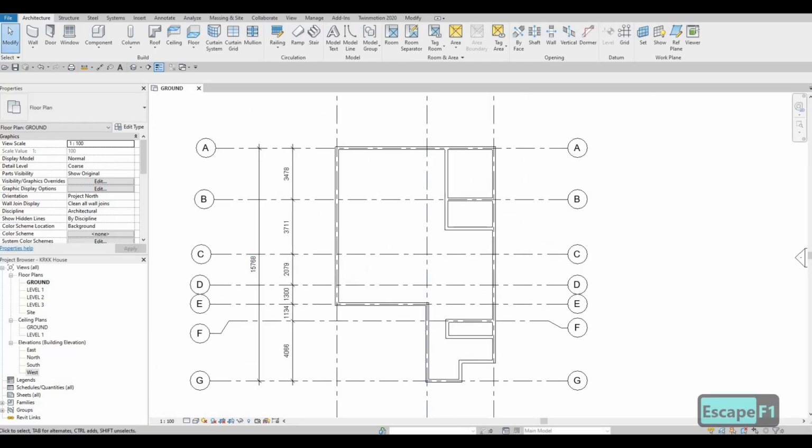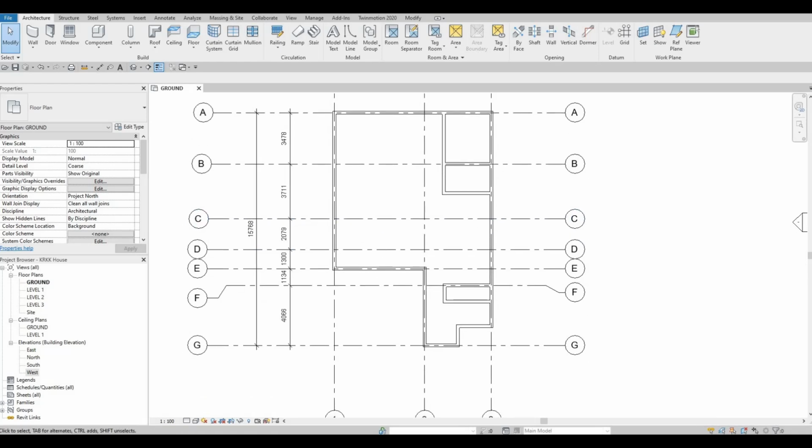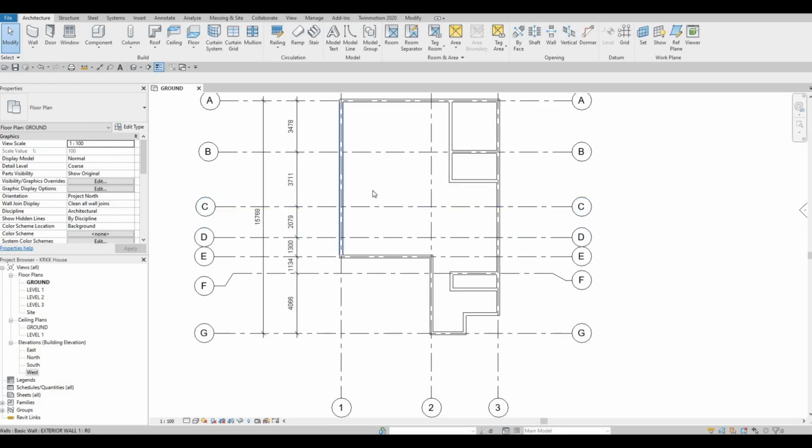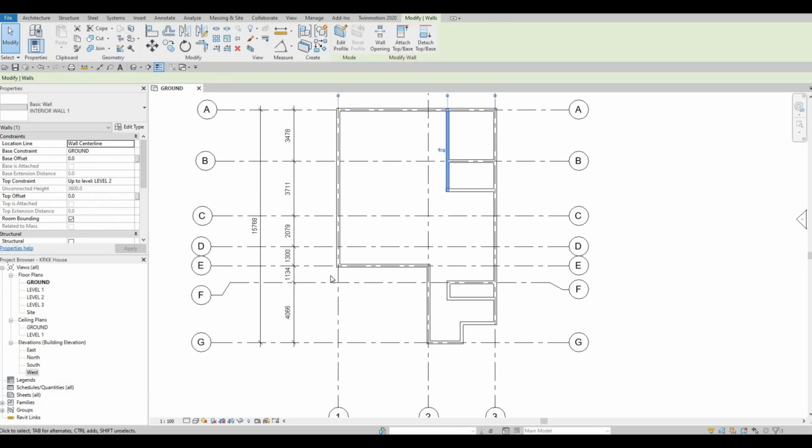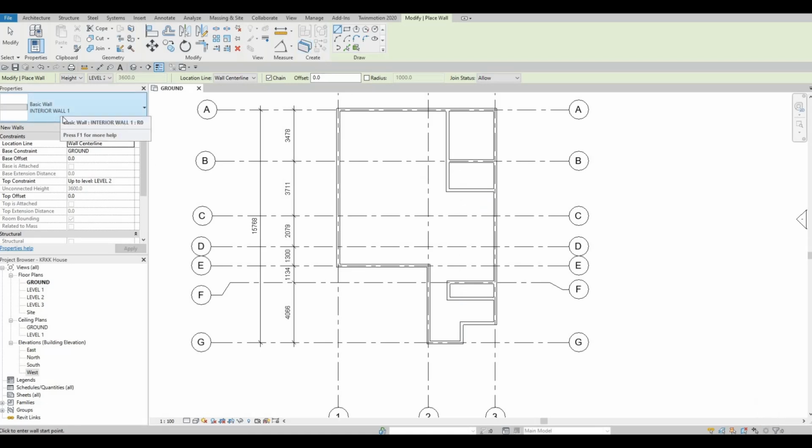Then I'm going to add the pantry around here. This will be going to the C. So I could select here and then type in CS. What it does is I'll be able to instantly add interior wall or anything that I selected, so that I don't need to keep on looking for those. So that's create similar, which is right here under modify again.